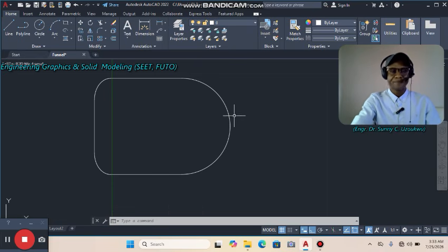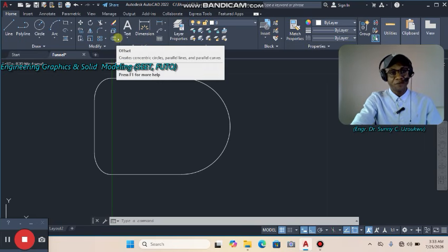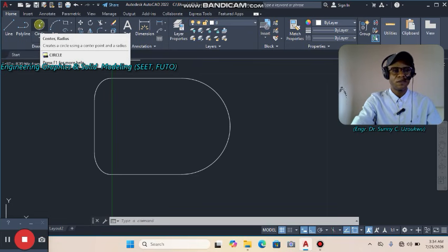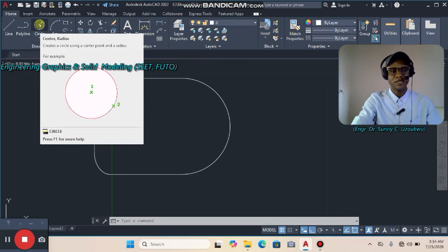Then very quickly, I was still working on the plan of the funnel. You know, we're working on the funnel, and I want to start with the 2D plan of the top view or the top part of the object. And if you watch closely, you're going to see opening of 2 different diameters. So how do you go about it? Let's assume the first one is 1 inch, the other one is maybe 0.5 or 0.45, depending on the interest or what's there. All right, next you go to the circle, or you say C enter, that gives you circle.